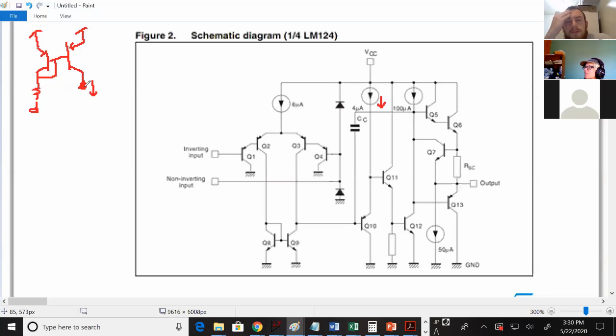Put a PNP below it. And then what's that called when there's two? You cascode them. Cascode. And then if you wanted a super duper awesome current source up there, what would you do? Cascode the other side too. The other side, actually, to bias it, probably is cascoded.